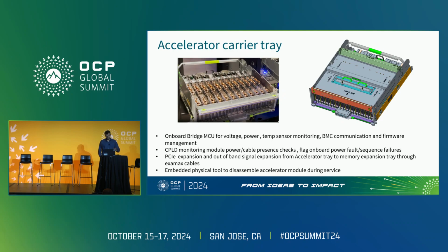The CPLD on this board, in addition to doing standard power sequence and reset control, also flags power faults, power sequence failures, and connection presence failures to the BMC for easier monitoring in the data center.